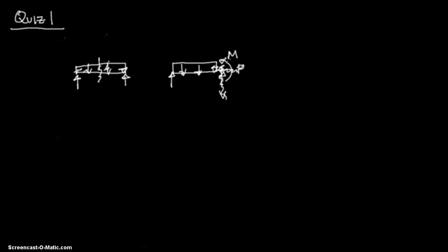Let's assume that for some reason we have negative, where we cut it, we have the moment that ends up being negative. So we get M equals, let's say, negative 20 foot-kips. Well, what that means is the moment's actually going the opposite direction.